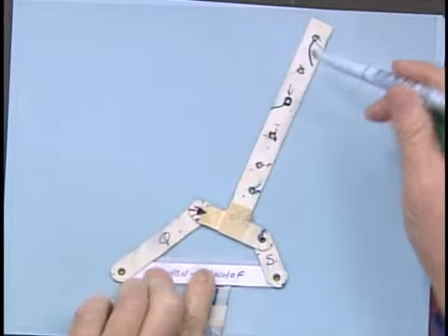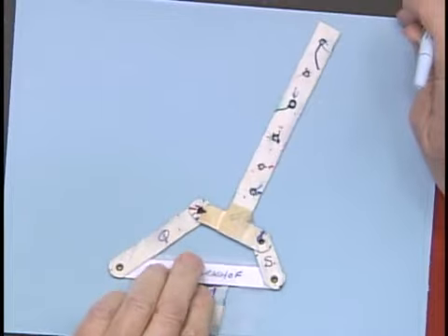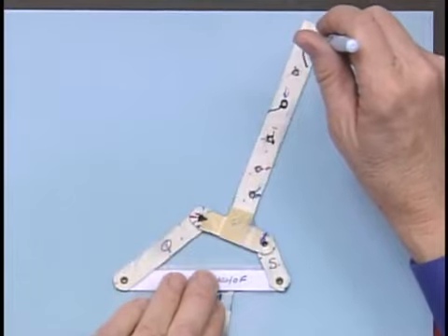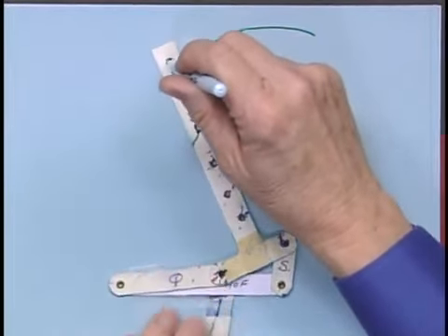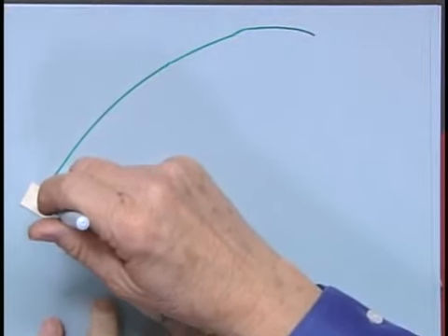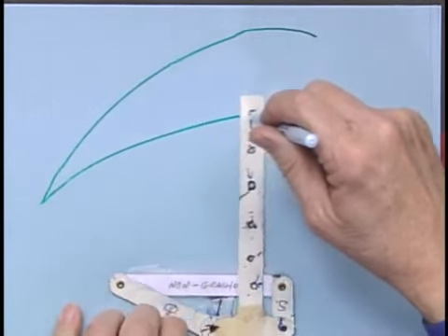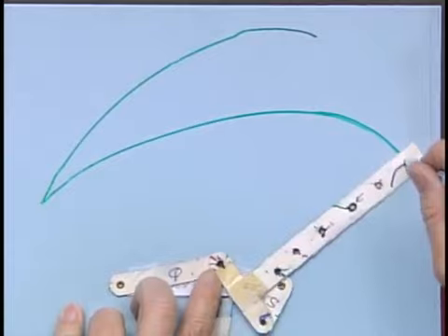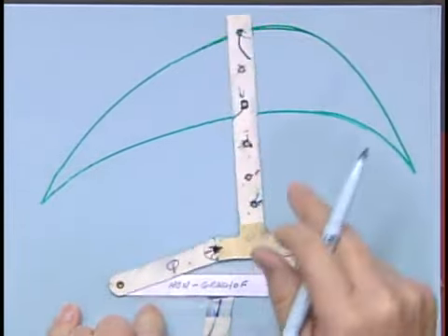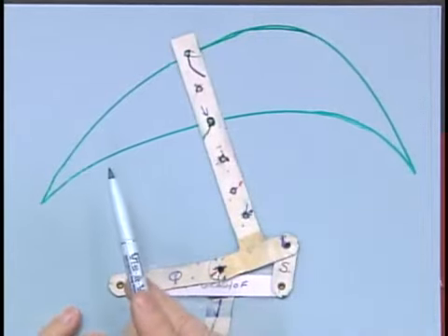But if I now go up on the coupler and I grab one of these points, let's say I take the one furthest out here as a starting point, and I try to drive it up here, I'm going to help the links through the toggle positions with my other hand. Okay, let's look at that one for a minute. My hand wiggled a bit at the top there. There shouldn't be double lines. It should trace exactly the same curve on each traverse.